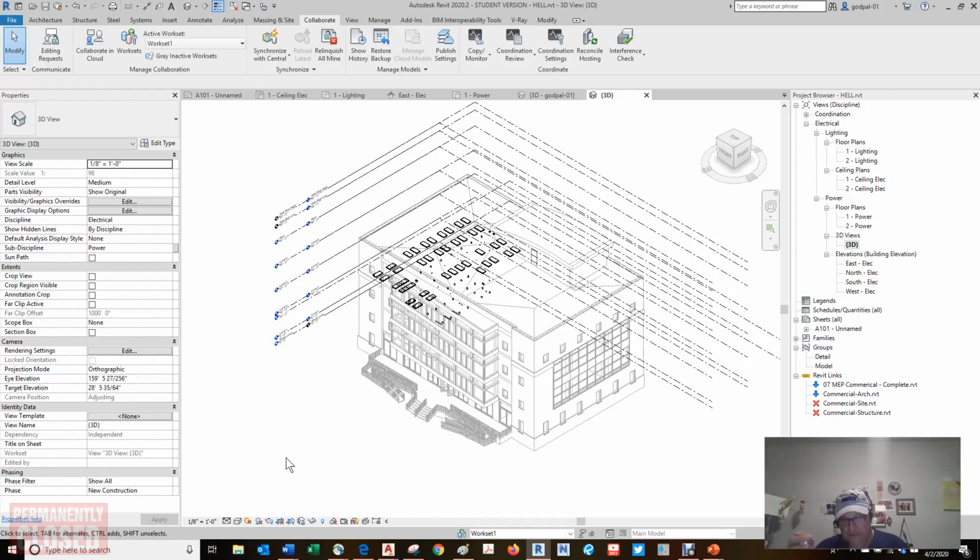All right. Be aware of that, because we're going to do it right now. We're going to mess around with the work plane a little bit. Most modeling tools and commands require an active work plane on which to place geometry. When you are working in a plan view, the work plane is usually set to the current level, right? You're looking at it. It's plumb, it's square. Let it stay there. If it ain't broke, don't fix it.